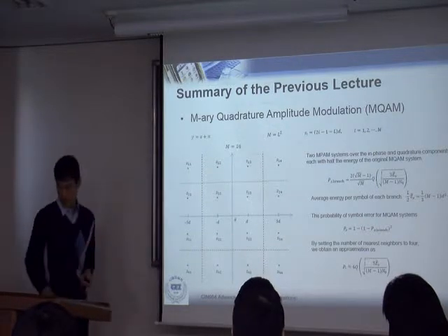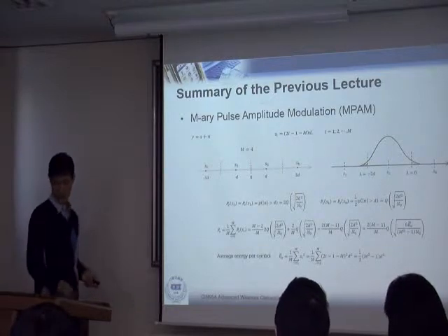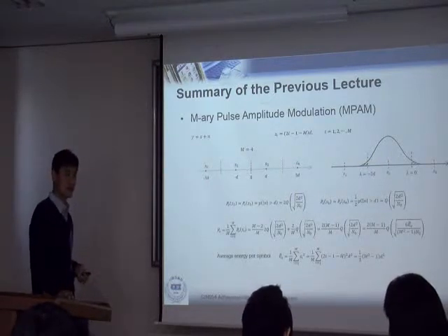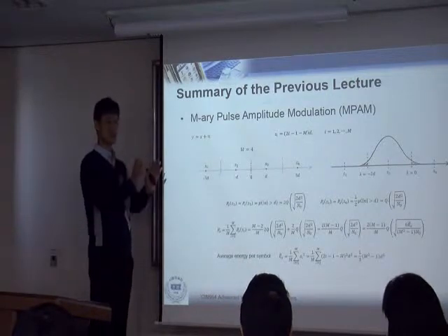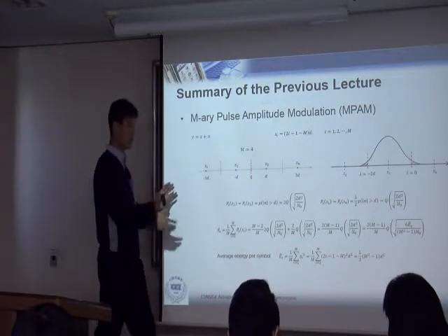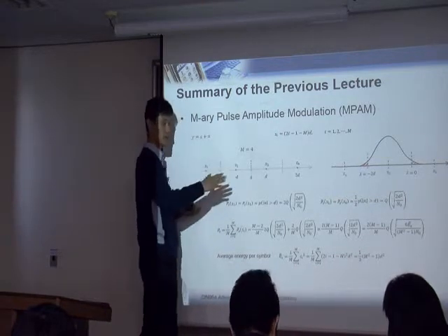To do that, we want to understand this one first. When I say QPSK, I said that QPSK is just as simple as 2 BPSK, right? One BPSK on the y-axis, the other BPSK on the x-axis.